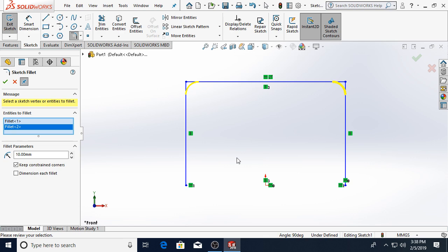So we have to create the center of this handle. We don't want it to be 0.075 meters, we don't want it to be 0.125, because both of those would be on the outside edge of the handle. One on the inside of the curve, one on the outside of the curve. We want the center. So we want a radius that's halfway between 0.075 and 0.125, which would be 0.1. If we didn't want to do that math to average the two numbers, we could have SolidWorks do the math for us. But whatever the case, 0.1 meters.